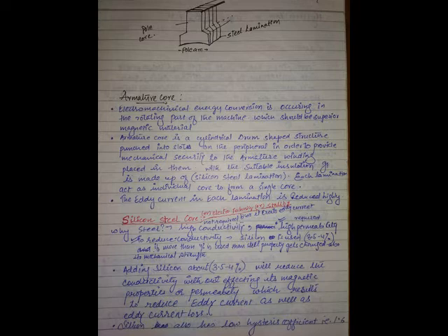Commutation plays such an important role in the operation of a DC machine. Why? Even though you design the DC machine to be excellent, with proper electrical characteristics, finally, if the brushes collect current with a spark, the machine is of no use.